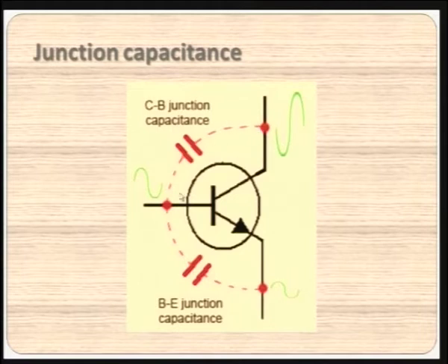There are two such capacitors, and how the signal is getting amplified with the phase reversal is depicted here. When we give a sinusoidal wave, we get an amplified wave with a phase reversal; when we give a sine wave, we get a minus sine wave here. In the emitter follower, there is no change in the phase, but we get a slightly lesser amplitude.